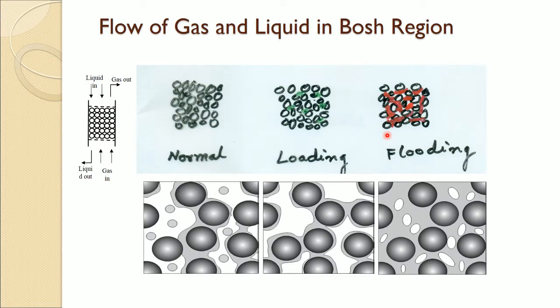So, we are talking about that, and we spoke about the liquid holdup. So, what is liquid holdup? I think before we move on to it, you should be familiar with this term. As you know, in the packed bed or in any packing, when you are flowing the liquid from the top and injecting the gas from the bottom, at a very low liquid flow rate and gas flow rate, you will see the liquid is just dripping through this packing and coming out, which is what we call a normal operation.